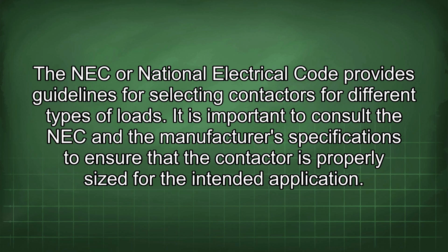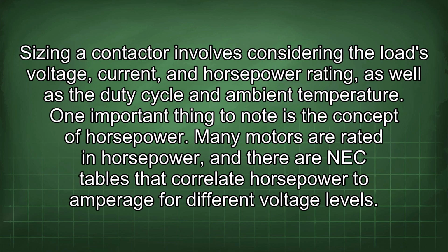It is important to consult the NEC and the manufacturer's specifications to ensure that the contactor is properly sized for the intended application. Sizing a contactor involves considering the load's voltage, current, and horsepower rating, as well as the duty cycle and ambient temperature. One important thing to note is the concept of horsepower. Many motors are rated in horsepower, and there are NEC tables that correlate horsepower to amperage for different voltage levels.